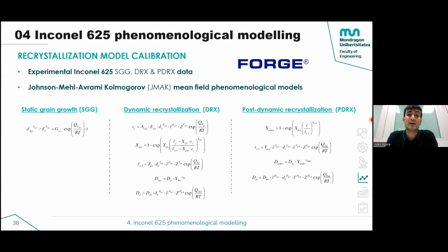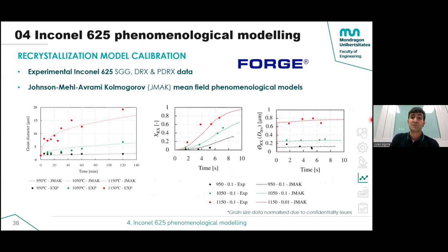In this case, we calibrated the typical JMAK mean field models, which are simple models, but could be interesting for the industry. And we calibrated static grain growth, dynamic recrystallization, and post-dynamic recrystallization models. Here you can see a comparison between the models and the experimental data.